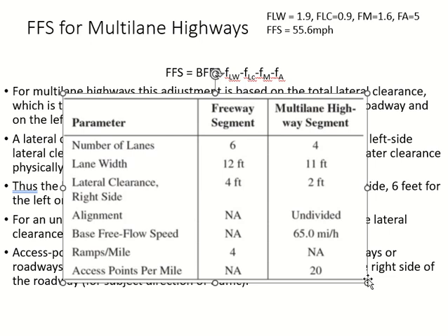Clear? Secondly, base free flow speed. We don't need it for freeway. We need it only for multi-lane highways. Ramp density. Freeways have ramps. Multi-lane highways don't have ramps. Access points. Freeways don't have them. Multi-lane highways have them. Clear? Okay, understood? So some of the things are only applicable to freeways, some of them are only applicable to multi-lane highways. So you can see the differences between them.